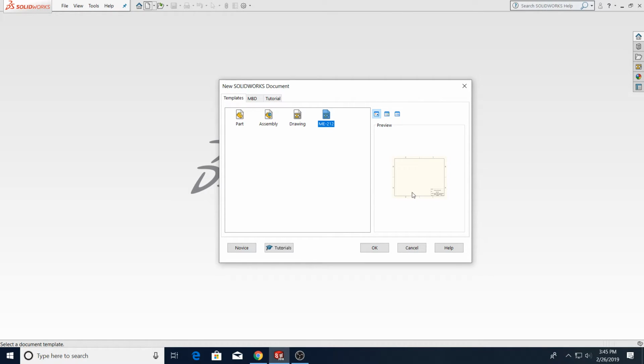As a side note, if I may pull a Zach Gutzmer, as an aside here, if you wanted to, you could create file templates that included features. Like if you found yourself working at a facility where you were constantly making rocket fins, you could create a default rocket fin, save that as a template, and then create a new rocket fin by just opening up that template. Then make whatever modifications you want to and save it as a new file. That way you don't have to start from scratch every time.